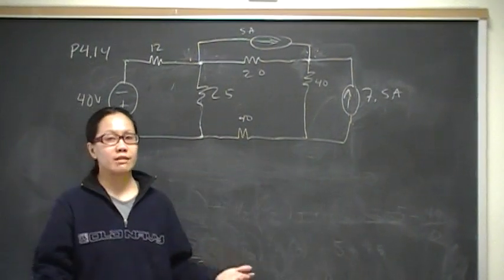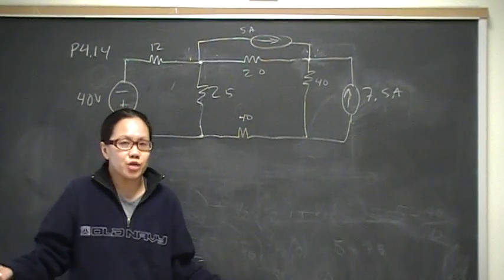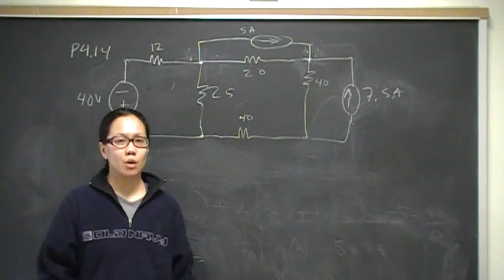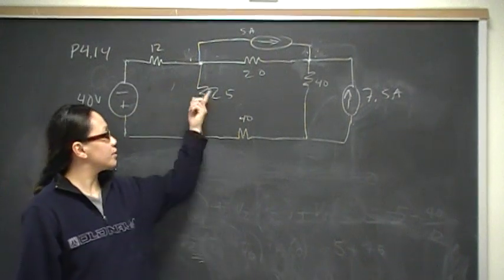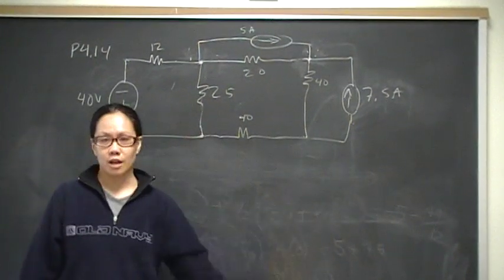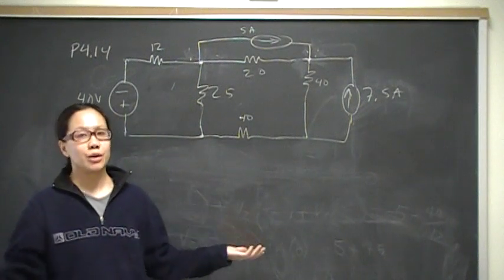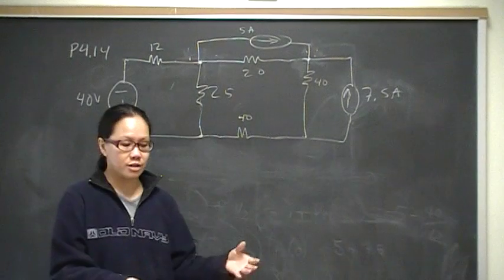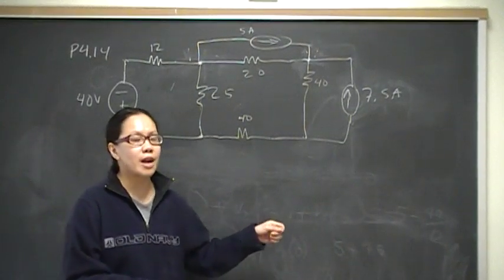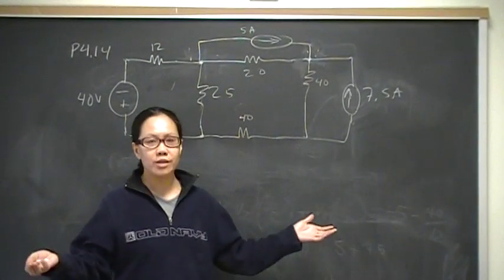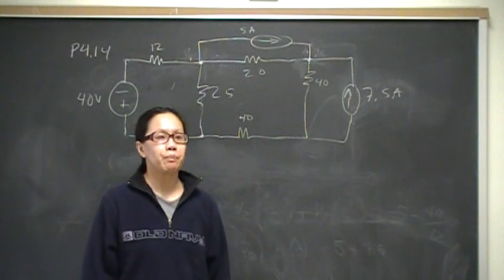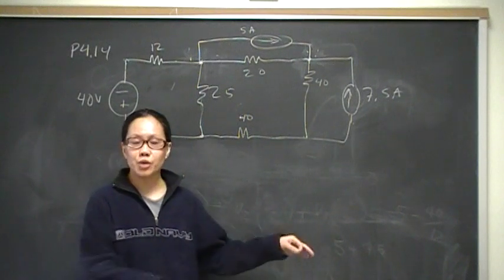Basically, when you're doing circuit analysis, what are you doing? You're really trying to find useful information like what's the current going through here, what's the voltage drop here. That's what technicians are always doing. If there's a problem, what do you need to know? You need to know the voltage. You need to take voltage drops and then find out if you have an open or a short and see where the problem is. Or measure a current.